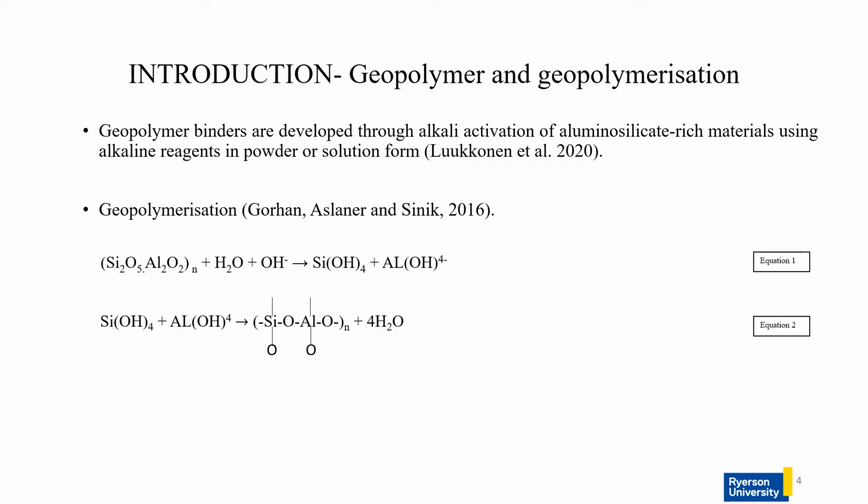Using the geopolymer technology or geopolymerization, geopolymer binders are developed through alkali activation of aluminosilicate-rich materials, which are also called the source materials or the precursors to the geopolymers, and using the alkaline reagents, which can be in powder form or solution form.